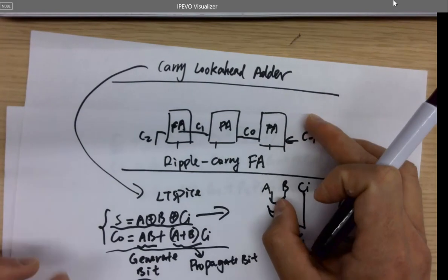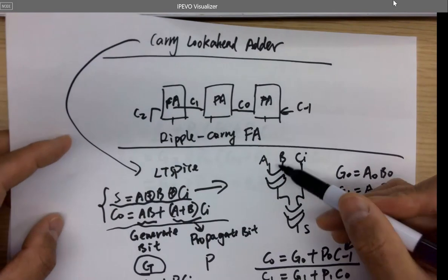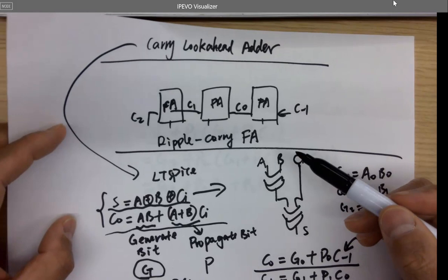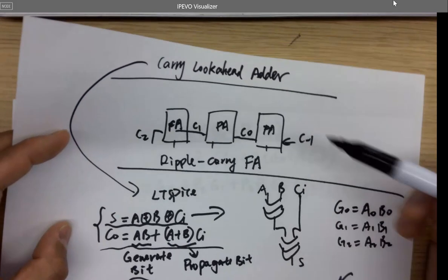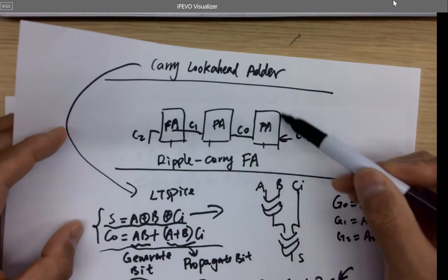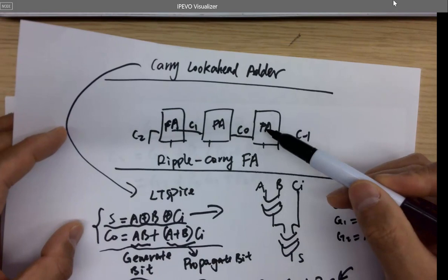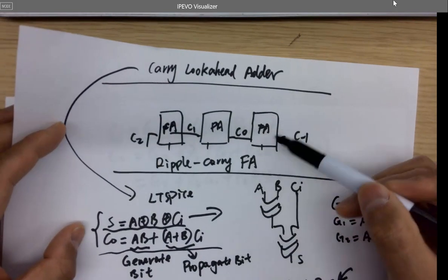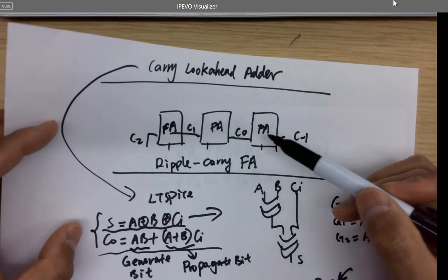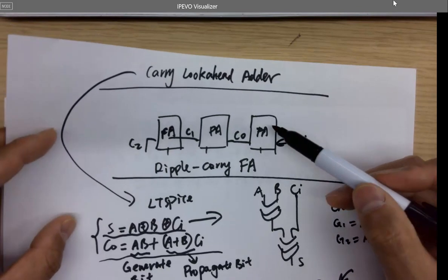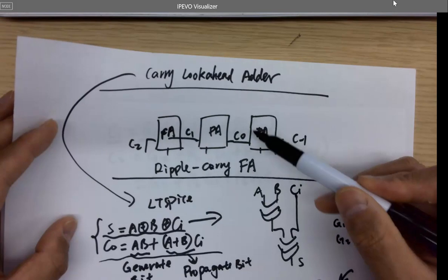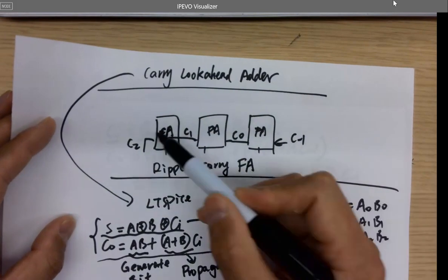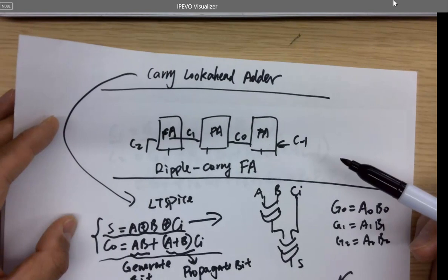What I will do is have all the logic gates, like XOR and OR gates, available in one folder so you can reuse them. Then you have a 1-bit FA in your folder, and you start another schematic so you can reuse the FA in that schematic. You can just place 3 of them in the schematic, make the connections, and do the simulation in that schematic.